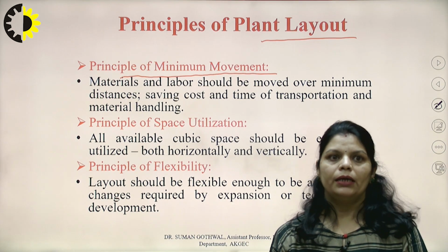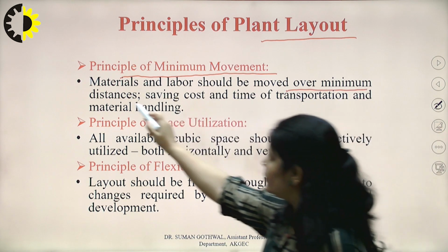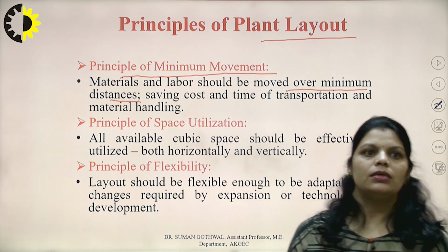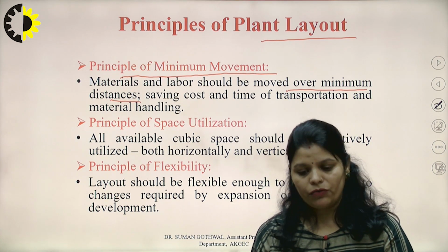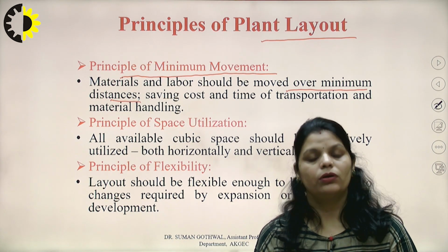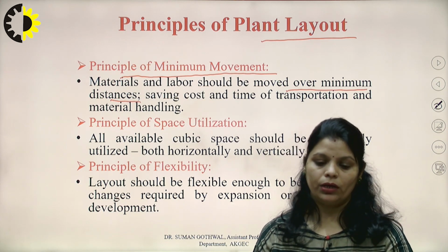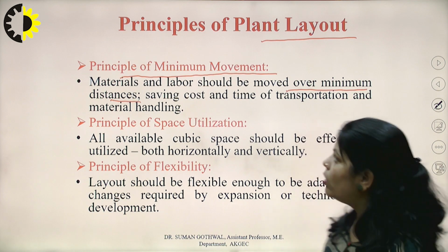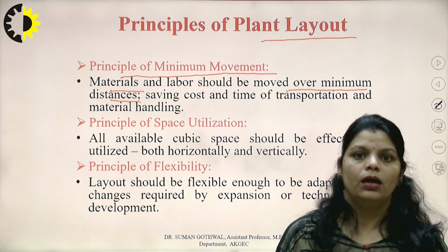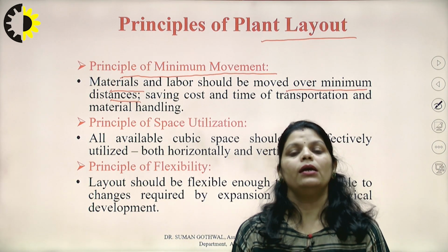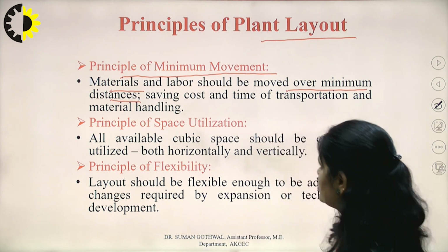It means the materials and the labor should be moved over the minimum distance. Our objective should be, whether we are talking about the operators working on different workstations or about the materials, to minimize the movement between different workstations.